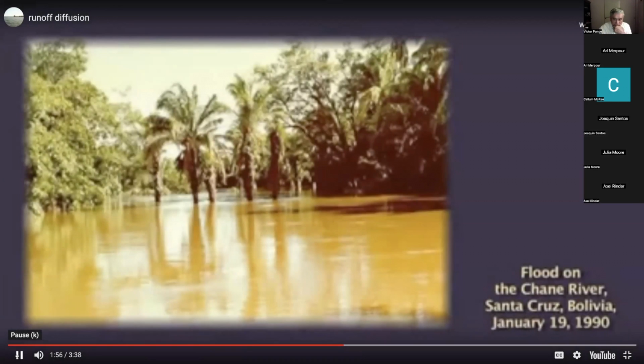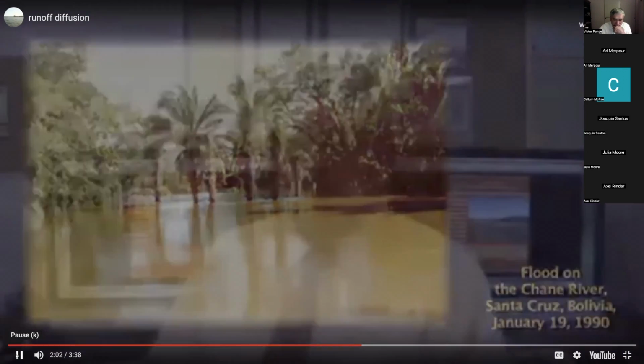Flood routing is the calculation in time and space of a flood hydrograph based on the geometric and hydraulic stream channel characteristics. For small unit width discharges and or large prevailing slopes, runoff diffusion may be effectively reduced to a negligible amount. A flood wave that is not subject to diffusion is referred to as a kinematic wave.